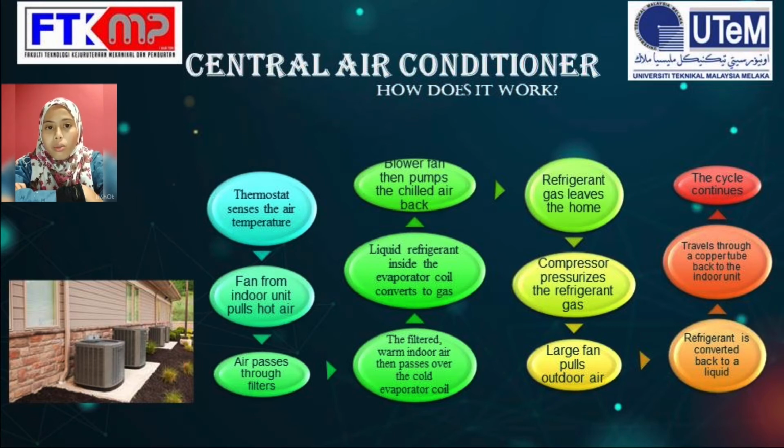The filtered warm indoor air passes over the cool evaporator coil as the liquid refrigerant inside the evaporator coil converts to gas. Heat from the indoor air is absorbed into the refrigerant, thus cooling the air as it passes over the coil. The indoor unit's blower fans then pump the chilled air back through the home's ducts into the various living areas.